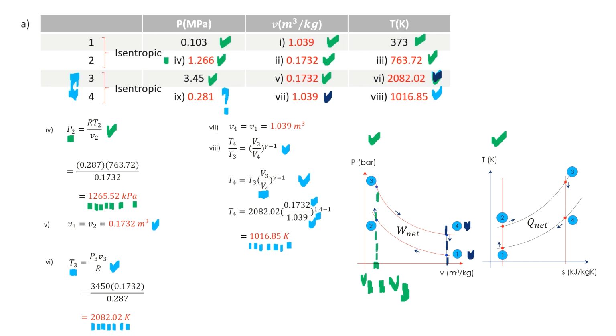So then now, the next thing is your pressure P4. So you can apply the ideal gas law again. You can apply the ideal gas law now here, because you have got this value and you have got this value as well. So now, apply the ideal gas law, you can find out your P4. Sorry, this value here. Okay, so you have found P4. So I erase it off. Okay, so that means the table now is complete. So once the table is complete now, it is easier for you to find whatever is to be found.